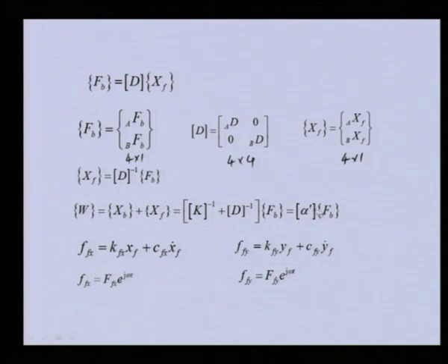So, basically you can see now this is an effective influence coefficient which we obtained, and this can be used in the previous analysis instead of the bearing only. This particular influence coefficient contains the information of the flexibility of the bearing as well as the foundation. So, now we can consider the shaft flexibility, and then this can be added. From here onward the analysis will be identical to the previous one.